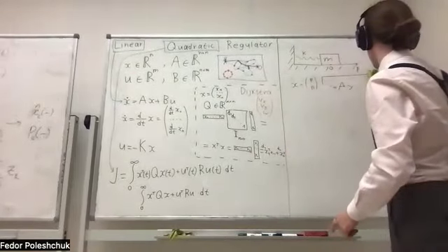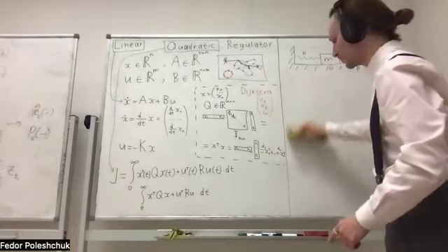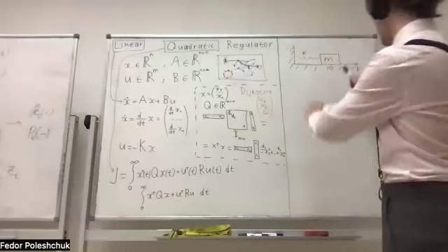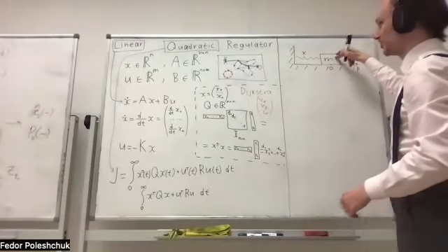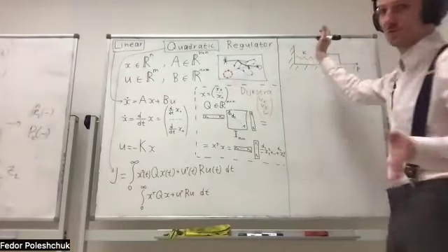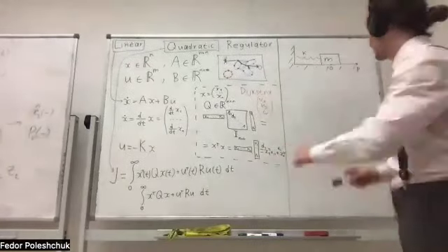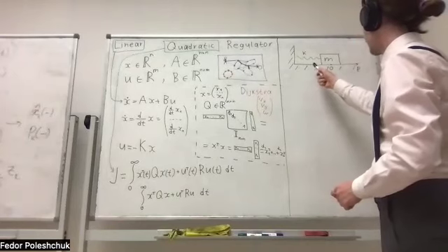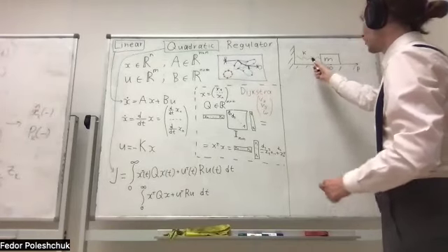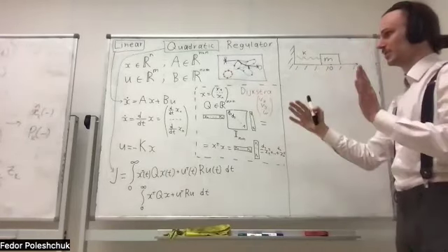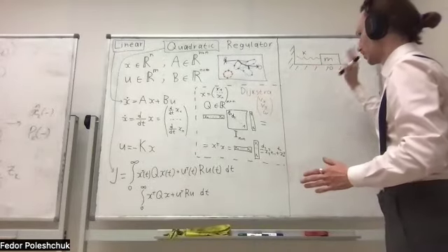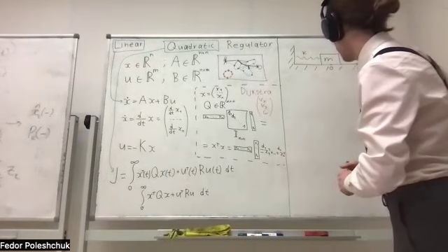Try to drive it to 0 in terms of the coordinate and velocity. So you have this block, you can set the mass to say 25 and the stiffness to whatever, it's not important. And the position of the spring when it's free, I mean not compressed, should correspond to the 0 position of the block.